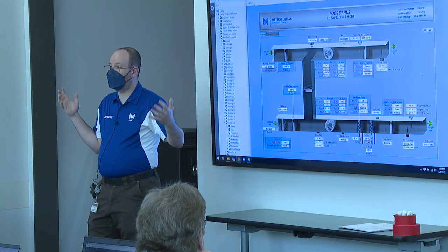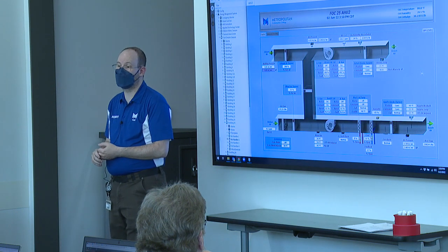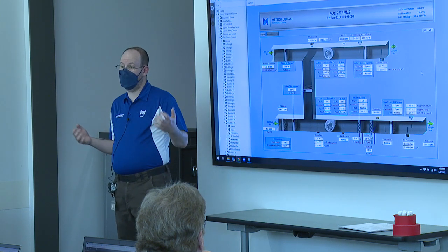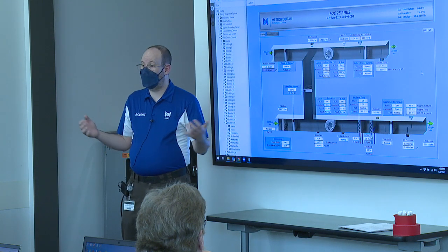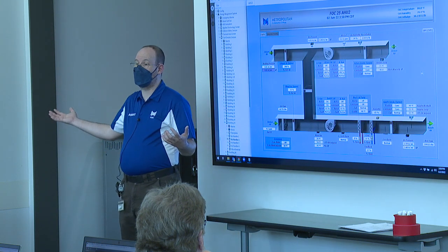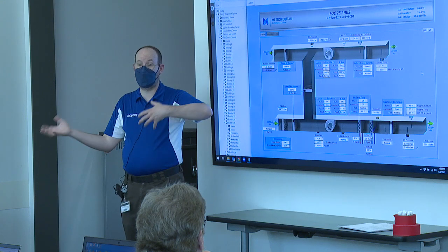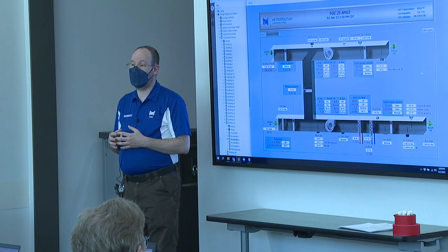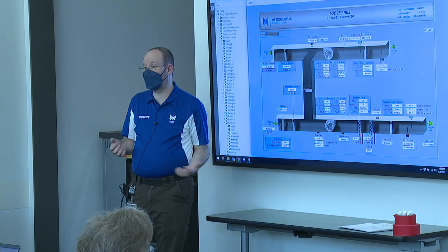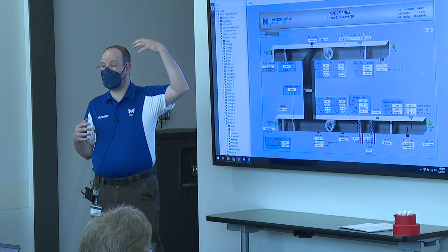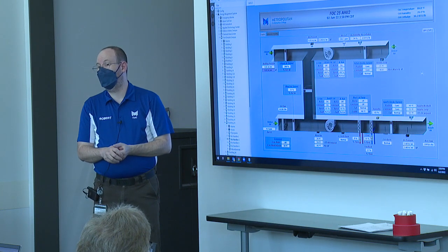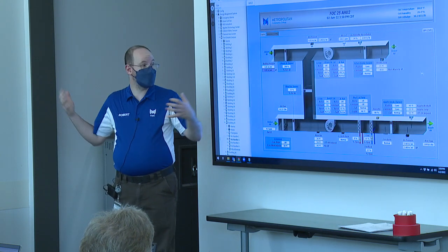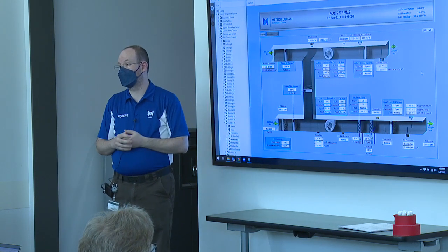Be honest, that's fairly uncommon for new buildings. Retrofits in existing buildings, updates, remodels, much more likely. Okay? And when in doubt in those situations, if you still can't talk to the operator, match the old, or try and match what was there. With new buildings, oftentimes it's dictated by the engineer what they want to see on the graphics because they think that that's what the operators need to see, and in combination with what the building controls technician has done in the past that has worked.